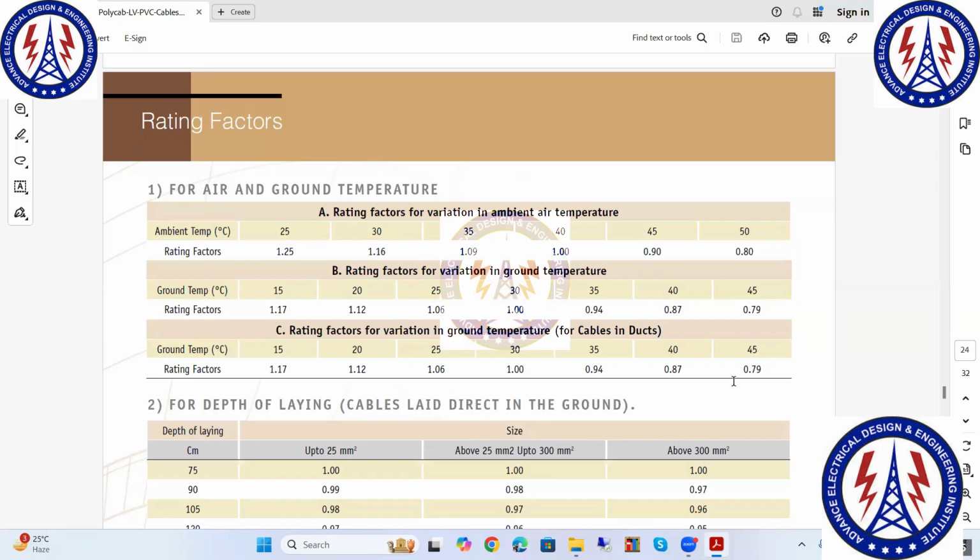Generally, equipment is designed for 1000 MSL. If the altitude is more, then definitely derating will happen, and the manufacturer will tell how much we need to derate.